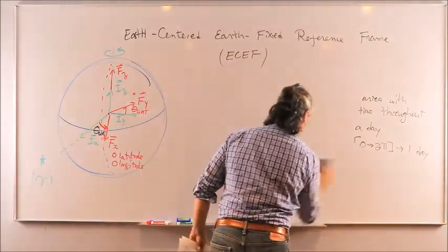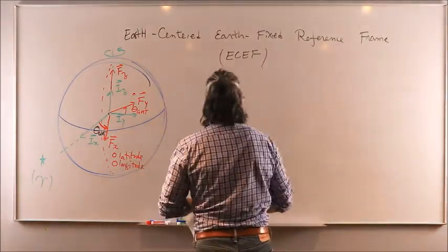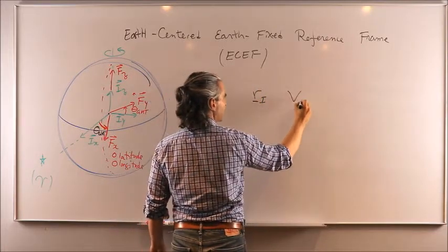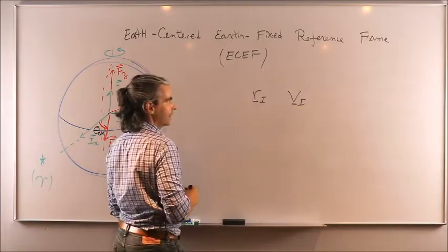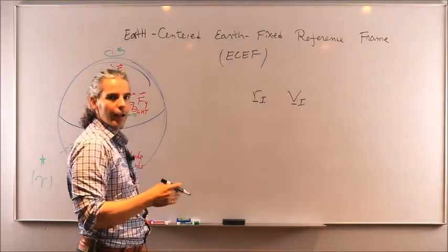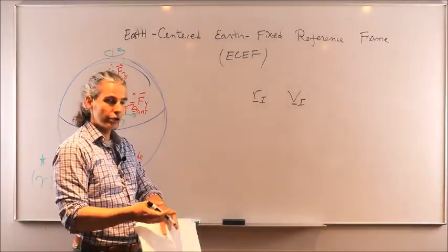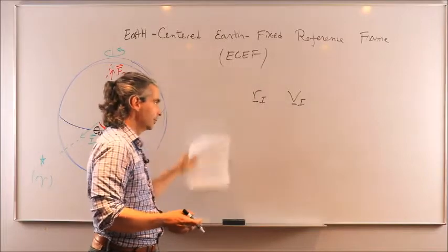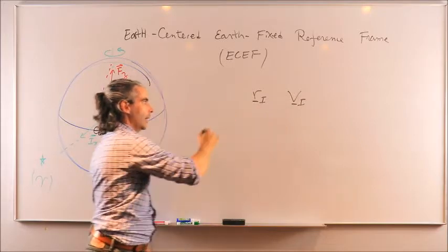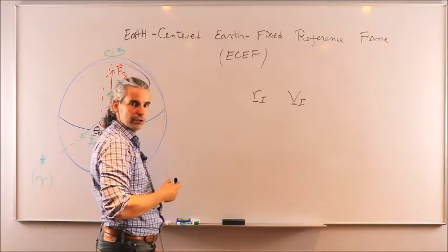Well, this is not too difficult, because if we have the position components and the velocity components in ECI, X, Y, Z, all we have to do is convert those into ECEF, and then from the ECEF components, calculate latitude and longitude, and then plot latitude versus longitude on the graph, and we would see those sine waves shifting to the left one after the other, as multiple orbits are being executed one after the other.